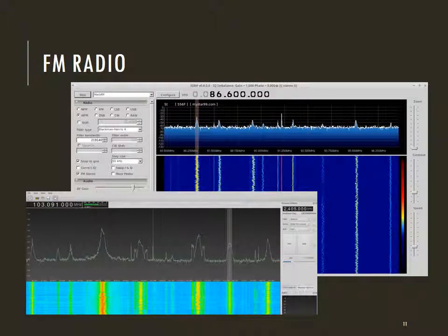On this slide, we see the results of the experiment configuring the software-defined radio, SDR Sharp, to use the wideband frequency modulation, or WFM, using the Blackman-Harris 4 filter and tuned to the 86.600 MHz frequency using a 50 kHz step size. We can also see the data transmitted with the audio signal displaying the name and website of the radio station that is broadcasting, mystar99.com. The signal carrying the audio and the data can be seen visually on the waterfall graph in the screenshot.